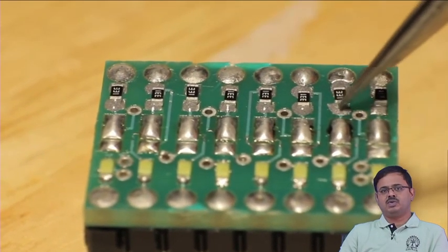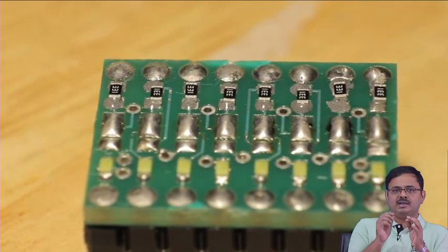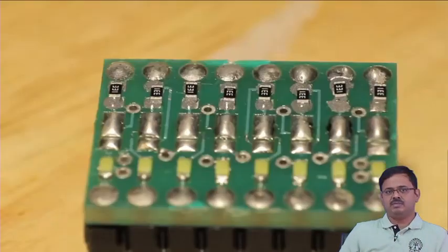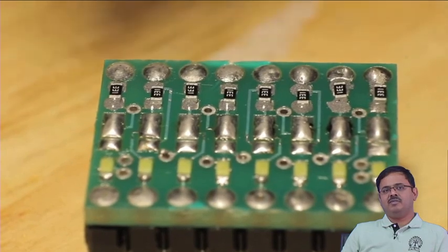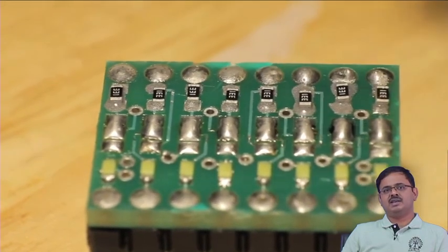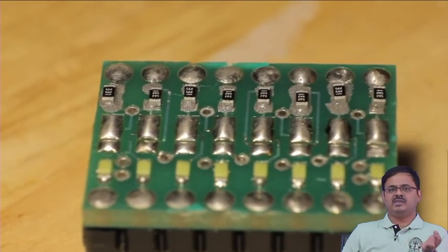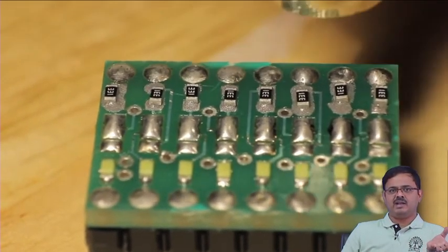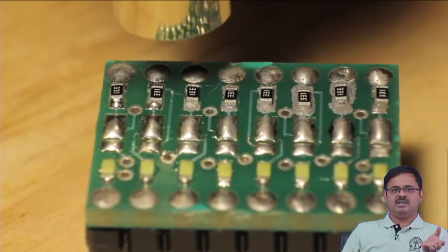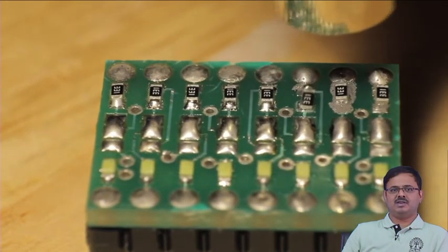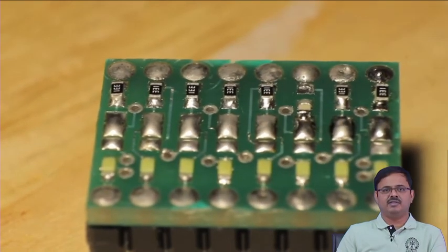Next, he is going to heat up, so that the solder on both sides melts and wets the joints. See what happens here. Here it is not a reflow oven. What the user is doing is, he has taken a hair dryer or some kind of hand blower, a heat gun, and you see they are all aligning, but the fourth one suddenly lifted off.